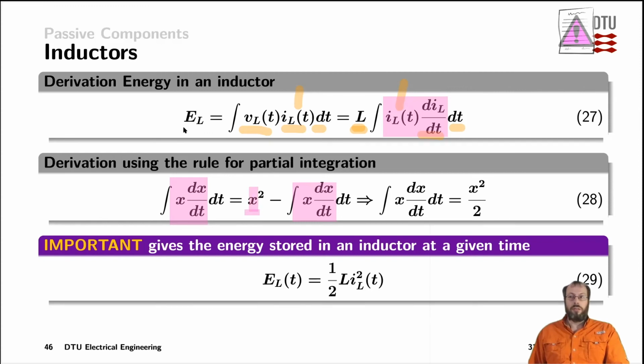As we wanted to derive a solution for the energy of the inductor in the first place, which is the integral over here times the inductance here, and our x from down here is the same as the current from up here, the inductor current. We can simply place the inductor current from up here into the equation down here, and that means we have a solution for our energy at the end, where the factor of a half is coming from the solution of the integral being set in here.